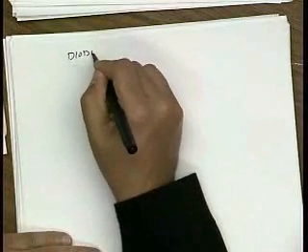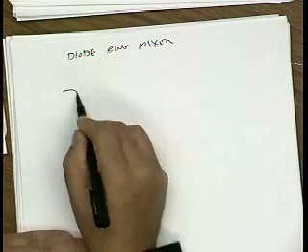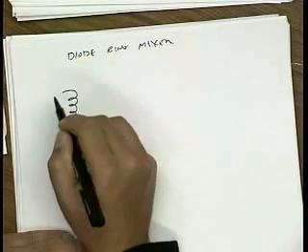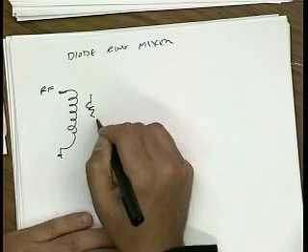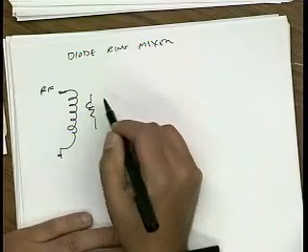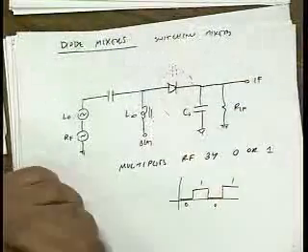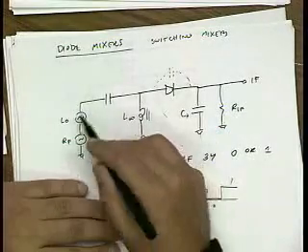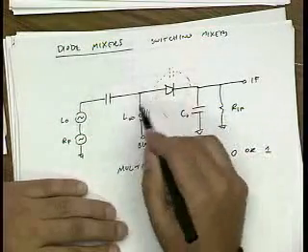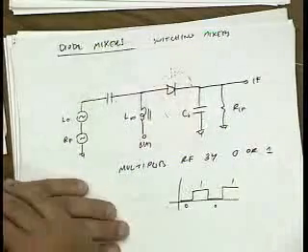Let's look at a diode ring mixer. Yes. Infinite inductor. So can we achieve this in reality? And what if we can't do an infinite inductor? It just needs to be large enough, right? We want most of our input signal to go through this path rather than this path. So if the impedance of this is about 10 times bigger than the impedance of this, it's going to do a pretty good job.